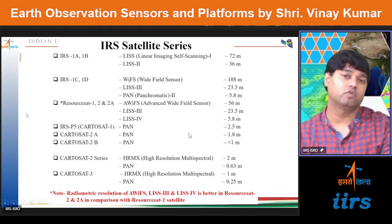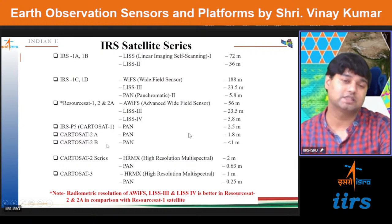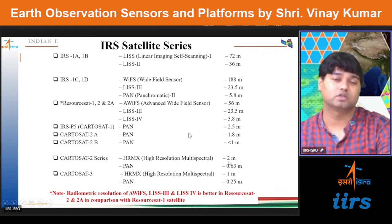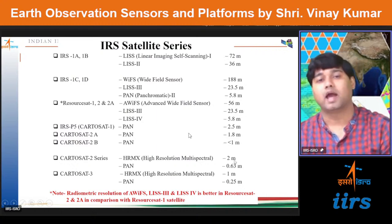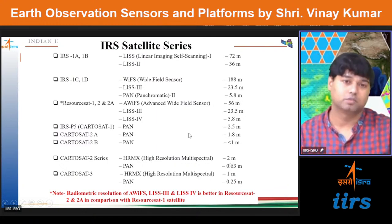Then Resourcesat 1, 2, and 2A have AWiFS, LISS 3 and LISS 4. But the difference is that Resourcesat 1 radiometric resolution is lesser than 2 and 2A. Then Cartosat 1 was launched with a panchromatic band with 2.5 meter resolution. The Cartosat 2 series, as I was telling, has around 0.63 meter resolution in panchromatic, and in multispectral it is 2 meter. And Cartosat 3 has 25 centimeter and 1 meter spatial resolution.